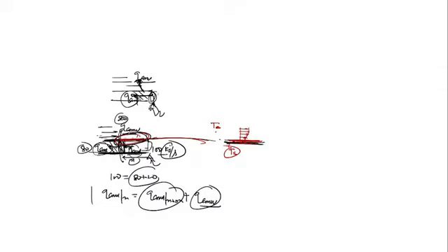But what I am saying is, when the temperature of the fluid and the surface differ, and there is a velocity gradient, that velocity gradient also causes a temperature gradient. Due to this temperature gradient, there is also heat transfer. Is this clear? So at y equal to 0 plus, just on the surface of the pipe wall, the heat transfer is through conduction only because the fluid layer is stagnant. Heat transfer is initiated by conduction, but due to motion in the fluid, at the first layer of the flowing fluid, the heat transfer is through conduction.